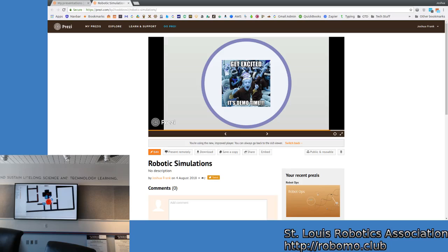So what I can do is give it a nav goal. You'll see as this drives around, it'll actually get a little smarter about where it is. So I'll just give it a really short nav goal, using the tools up here. And so what you're seeing now around it is the cost cloud. As it navigates, it looks at all different paths of where it might go, it weights those paths, and then it tries to find the best path inside the grid that it generates.